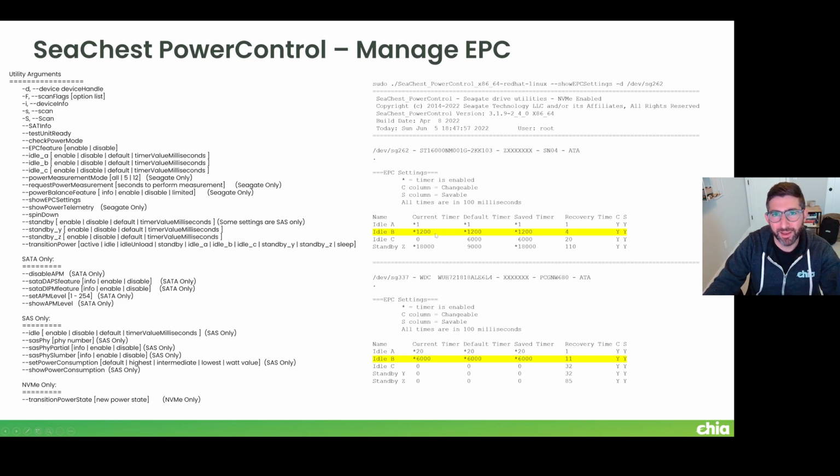And I mentioned that every once in a while with this default idle timer, over the course of a year, I've got a handful of load unload cycles. So ideally, on a Seagate drive, you'd want to turn this off or set that timer higher. If you have the default settings, it's really nothing to be concerned about because you're just doing a few a year, and you're completely well within the range.